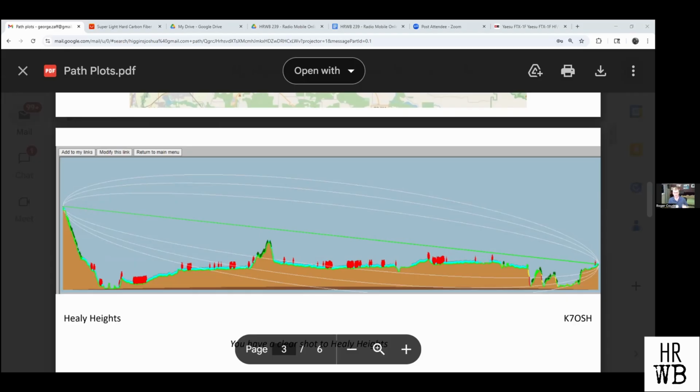There is the ground loss caused by the obstruction of the ground, and there is a penetration loss through the buildings and the trees. In this case, it's only buildings that are in the way, or a little bit, okay. I had to make some simplification. So I consider only the trees and the buildings that are within the first Fresnel zone.